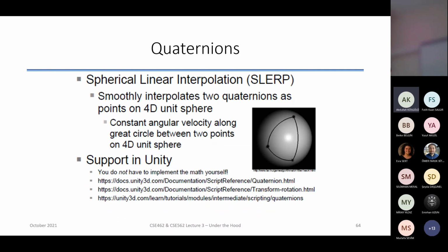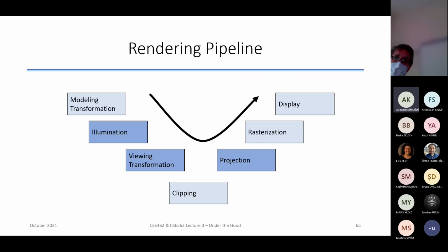Now, this is important because you need to understand quaternions to represent rotations. Otherwise, the rotation matrix itself, even though it has 3 degrees of freedom, is a 3 by 3 matrix. So this is not a reasonable representation. If you want to represent this in a parameter form, you have to have non-linearities inside. So let's go back to the transformation. You have to associate one model or coordinate system to another coordinate system using this.